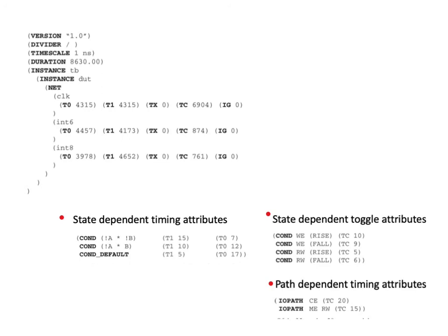the simulator will generate backward SAIF files that give you per-net statistics of the toggle rate and the probability rate, but you will not be able to derive the toggle rate under certain particular signal conditions.